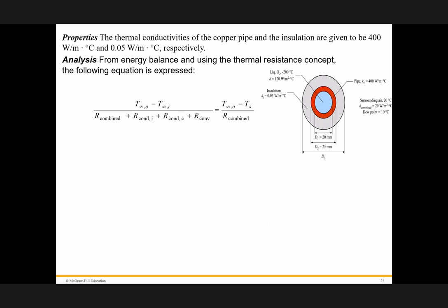Okay. Any question, please? Therefore, this is simple energy. We wrote a steady state scenario, and we mentioned from inside to outside is equal to from outside here. Yes, sir. The right part of the equation is from the surface to the surrounding air. That's correct. This is the outside temperature. It is 20 degrees. This is the surface temperature, if you like to put 10. So all combined is just h, right? That's right. This is the only part.